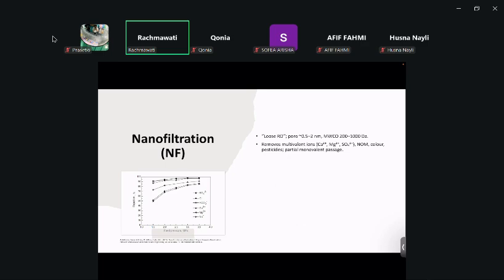Or if there is natural organic matter, or if there is coloring in your water. Suppose your water should be colorless, but it's quite yellow because maybe ions are there. You want to remove them, or probably there are pesticides. Maybe your home is close to an agricultural field where some fertilizers accumulate over time, and there's a high amount of ammonia in the drinking water, then you want to remove them. Or maybe some monovalent ions can even be removed by using nanofiltration, just some of them with size big enough with regard to the pore size of the nanofiltration.